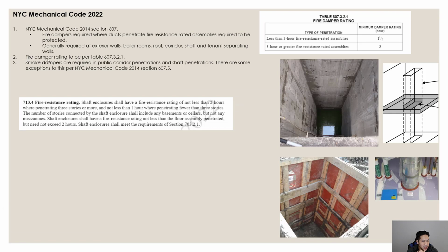Before we were talking about fire dampers. Now for smoke dampers, which are a little bit different, they basically operate upon sensing some sort of smoke from a smoke detector. And once the smoke detector detects the smoke, it'll send an electrical signal to an actuator, which is just a motorized damper that'll close. And that's what a smoke damper is.